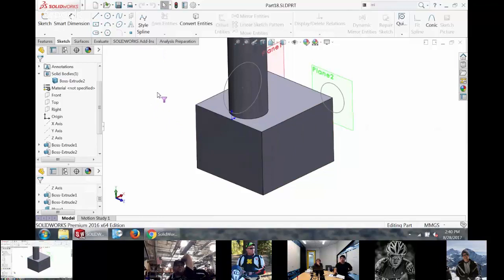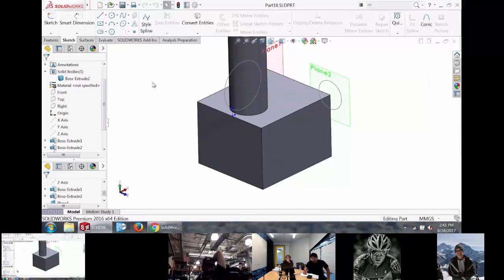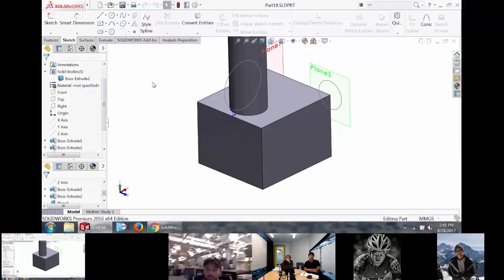So if you ever see that filter come on, you could start pressing E, X, V and see if that's the ones you did. Or the best thing is always just hit that F5 because this is a global, turns them all off. Hit F5 again, it goes away. And it is useful, actually. I use selection filters when I mean to. It's very useful. When you do it by accident, I can see that it's aggravating. But those are some of the ones that I've seen people, I get those questions all the time.